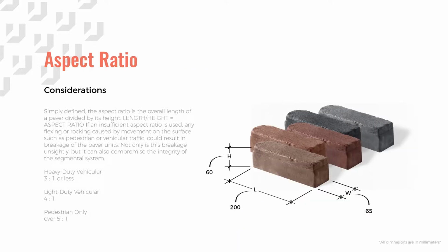Loading conditions are very important when designing a pavement, and the vast majority of the time they can be accommodated if considered during the design phase, ideally during detailed design. When the pavement receives a load, the base and sub-base components of the unit paving system carry the majority of the load. They must maintain strength in the presence of water for pavement stability.